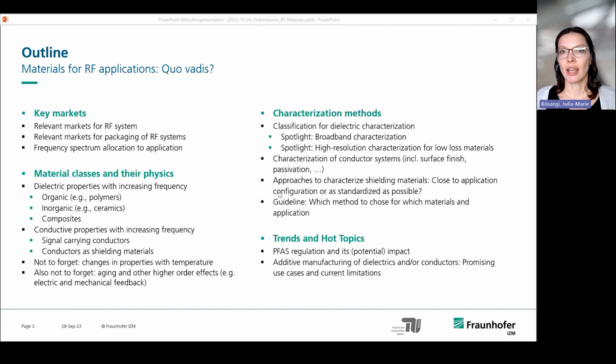We also see that the additive manufacturing technologies are advancing more and more, and with that we see better performance, because in the end the limit for the performance is the conductivity of the core material, the copper, for example, or whatever material you use in your additive manufacturing process. And while this is proceeding, we can use it more and more also for RF applications, where in the past maybe the quality has not been good enough.